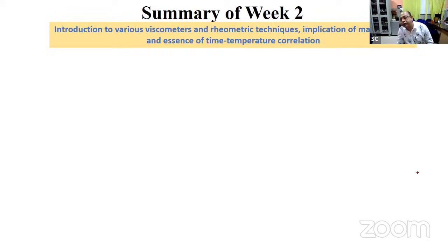One thing I must tell you. Some of you asked the question: DMA and geometric measurement, what is the difference? Measurement can be done in a static or quasi-static manner, where time is constant. Another way is to do it dynamically. You apply a dynamic stress and measure the dynamic strain, or apply a dynamic strain and measure the dynamic stress. From that you realize two numbers.